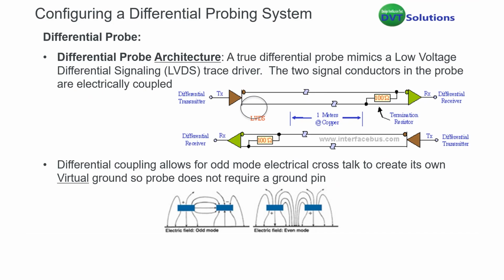So differential probe, we developed the first true differential probe back in around 2005 when the LVDS circuits started to come out from National Semiconductor and a few other companies. This changed the entire architecture at that time from point to point to a dual line differential interface. And it was designed so that you're able to reject common mode noise. So a power supply glitch, if it occurred, wouldn't just wipe out your data and your system crashes. It also allowed you to use a lower voltage to define the ones and zeros so that you can move data faster down a transmission line.